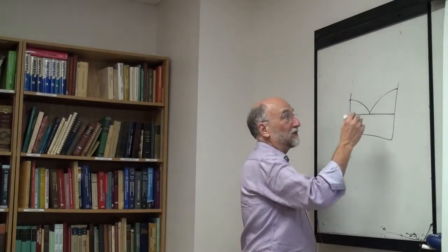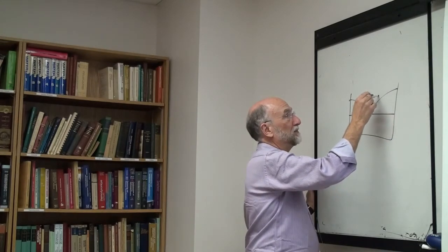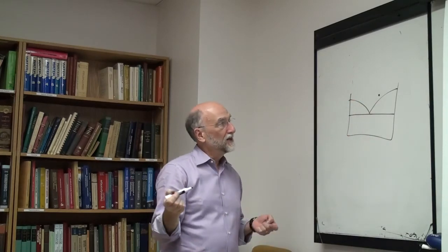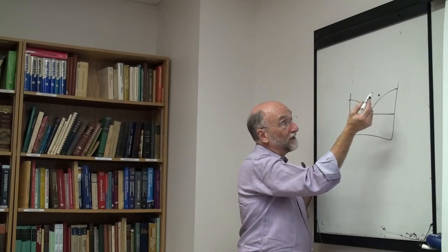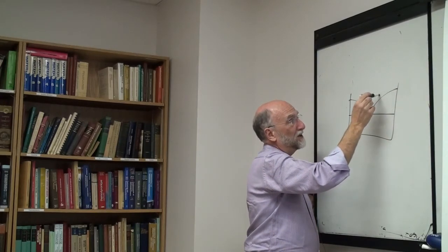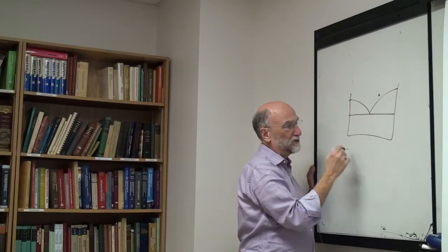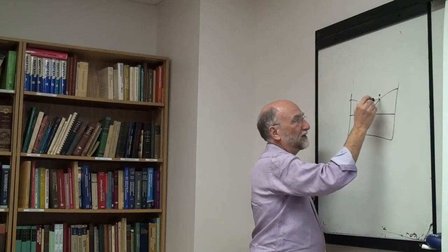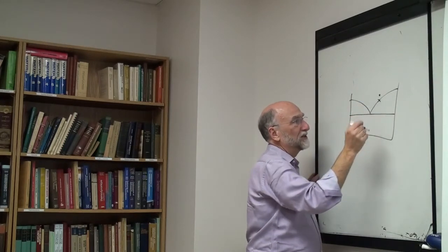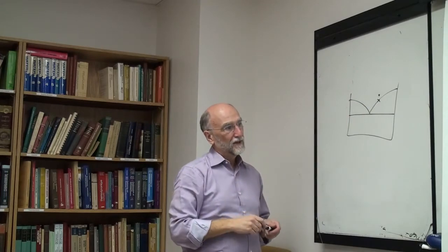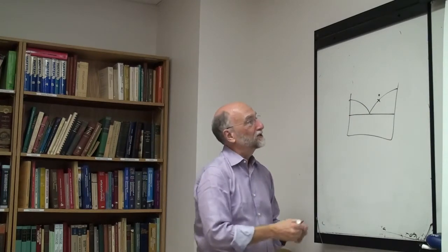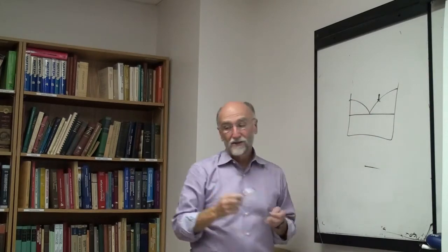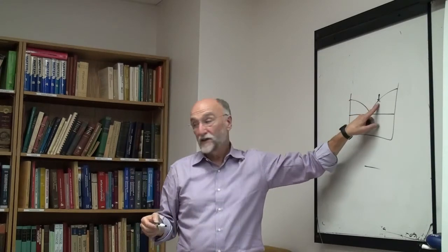The other way we do it is we're using some sort of a minimization routine. Basically, you're fitting everything directly. You have a liquidus point. This is what OptiSage does too. You have a liquidus point, say for example, and OptiSage takes that liquidus point. You tell it which coefficient. This is the equation that I want to fit the thing to, and it basically calculates using successive approximations. It guesses the value of the coefficients, gives you a calculated liquidus, and actually minimizes the distance between your experimental point and your calculated point.